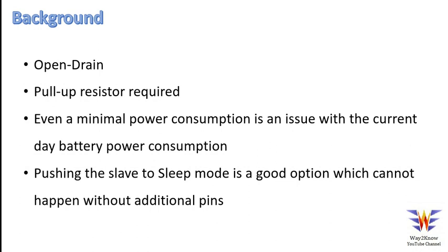And we know I2C is open drain, and for this open drain a pull up is required. The major disadvantage with this is that when you add a pull up, that adds to the power consumption, even though it will be minimal. But still, if you have applications where you have a battery, then definitely even nanoamps of current would matter there, right? And that is very important.